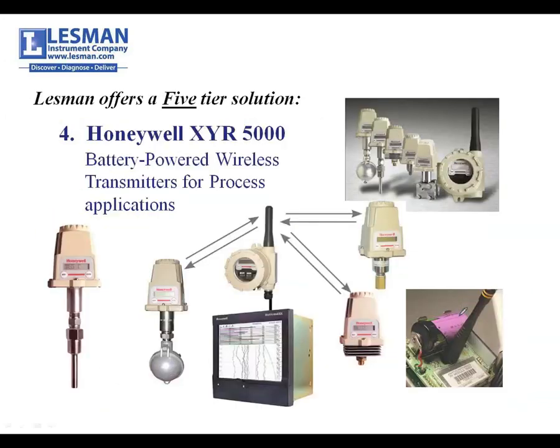Another variation that we have, this is a sensor-based radio network from Honeywell. These are a little bit simpler devices. They're a little better value. We can do temperatures, digitals, analogs. We can do acoustic inputs. You can have up to 100 of these field radios talking to one base radio. Okay, they're battery powered. Depending on how often you tell them to turn on and talk, they can communicate for up to 10 years. There is one highly available, non-proprietary C battery in this guy.